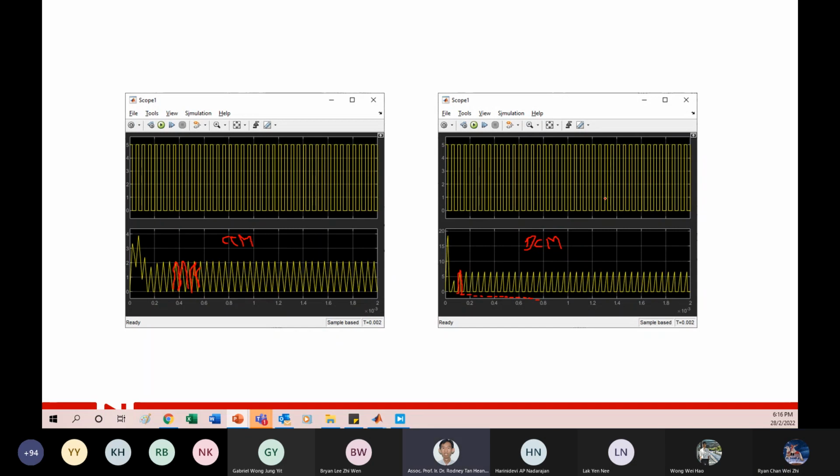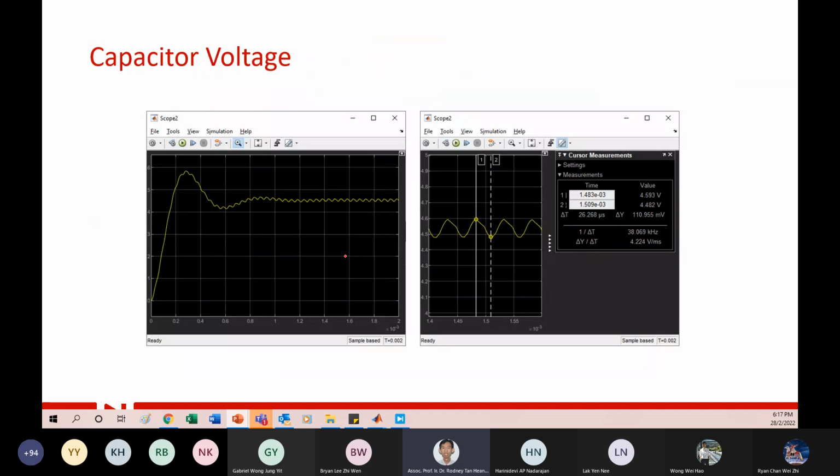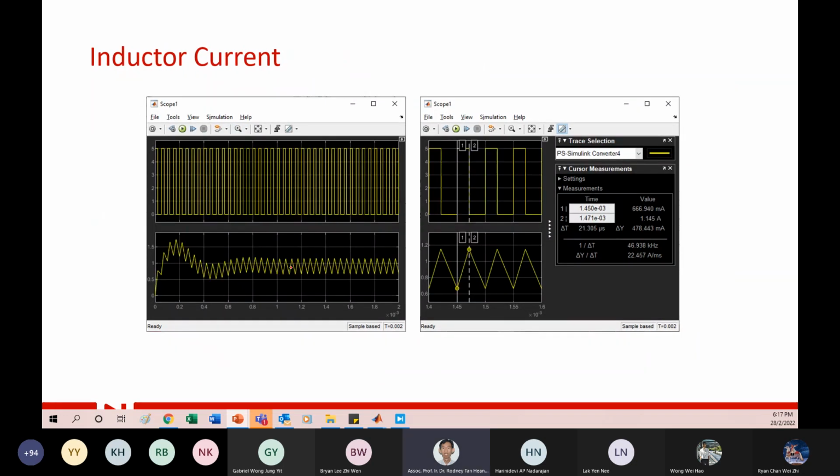To solve this problem, you either change the duty cycle, change the switching frequency, or change the inductor to a higher value. The smallest is when the discharge touches 0. But the one we design is way higher than the CCM boundary. So you see, no worry. You see the 0 is here.